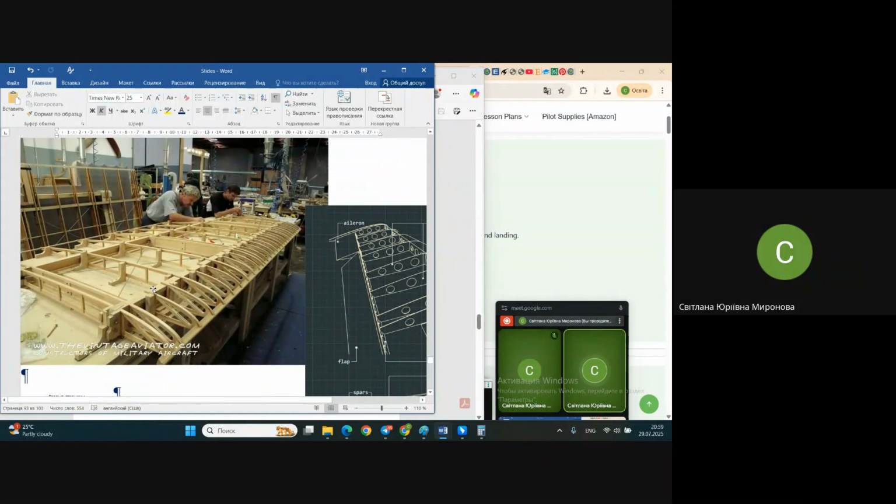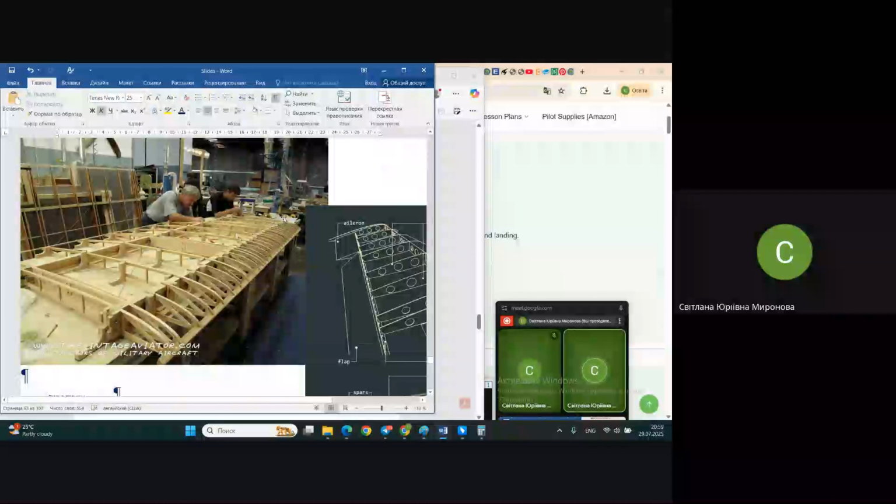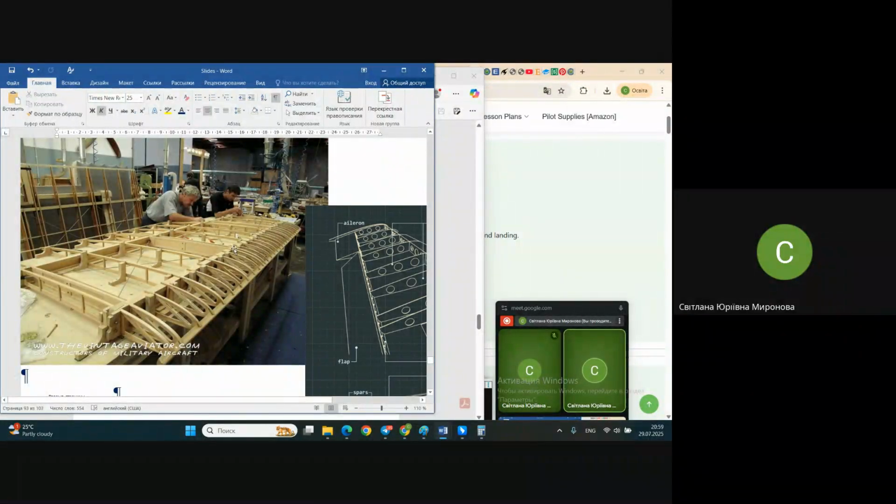Look, here the spar is extending from the beginning of the photo along the span to the back of the photo, and the rear spar. And those structures which are ribs are actually divided into subpieces. The spar is never cut. The spar is an important element working with bending moment, and it's the whole beam.